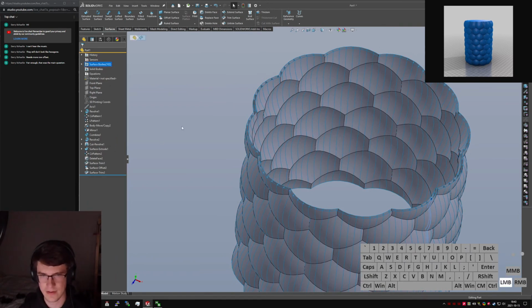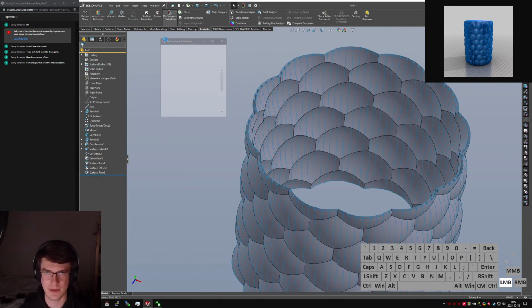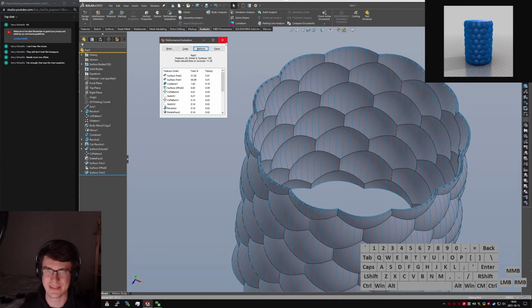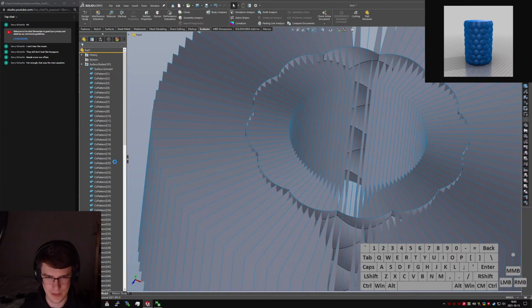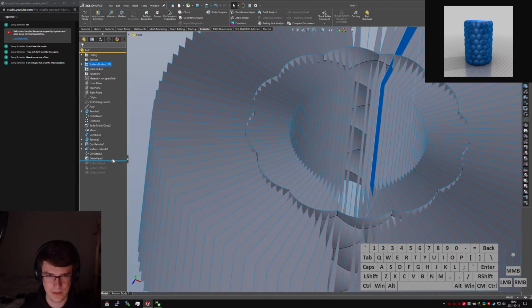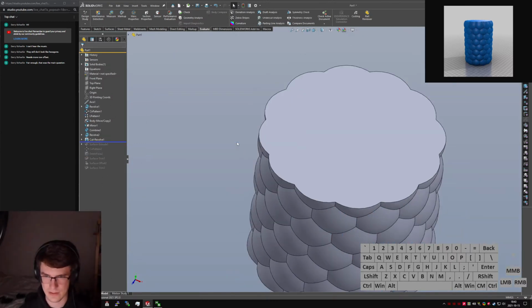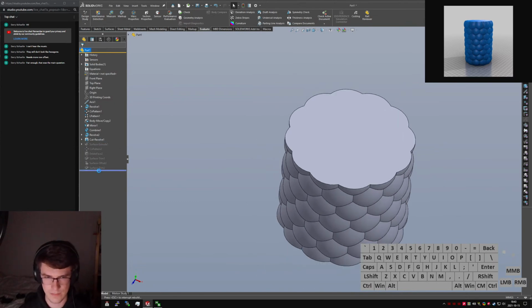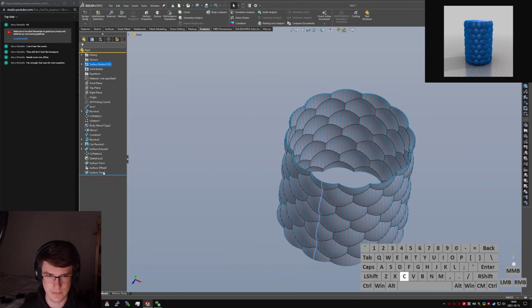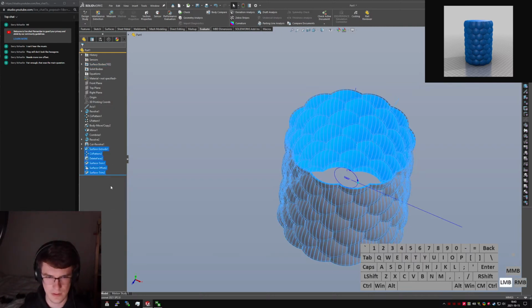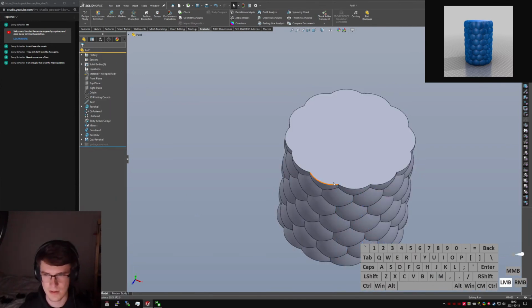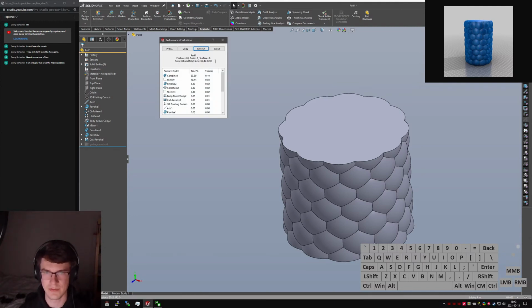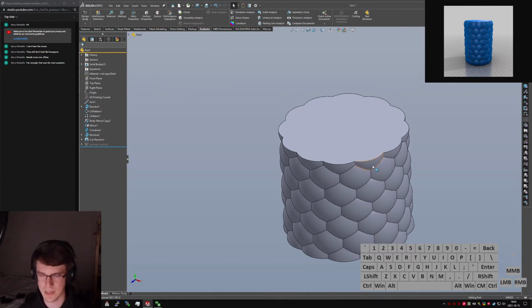Ooh, man. How are we doing? Evaluate performance. 11-second rebuild, that's not going to fly. Okay. That's not going to work at all. We're going to go back up before any of this. Well, let's Shift-C, garbage method, and then suppress everything in there, because it's all terrible, and we don't want any of it. Performance evaluation, 0.3 of a second. I can deal with that.